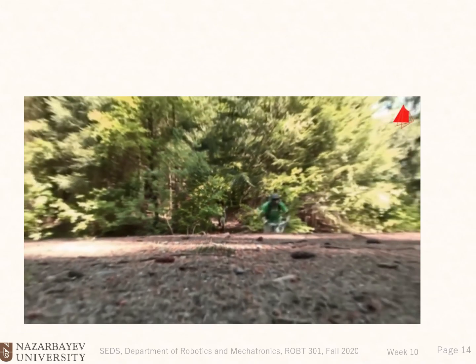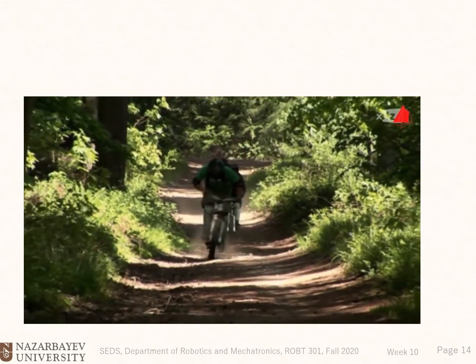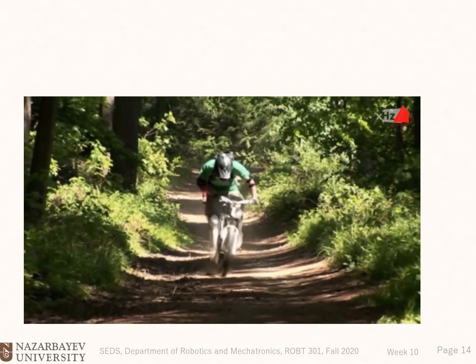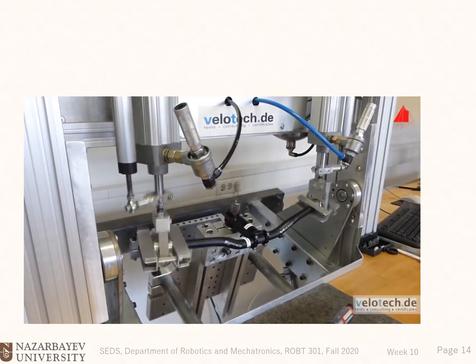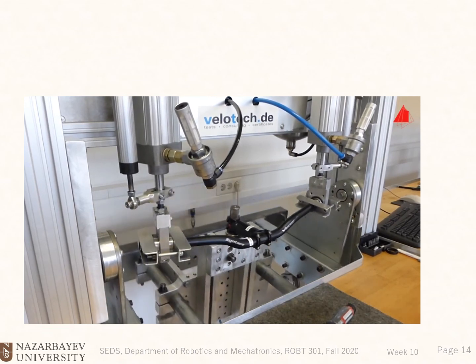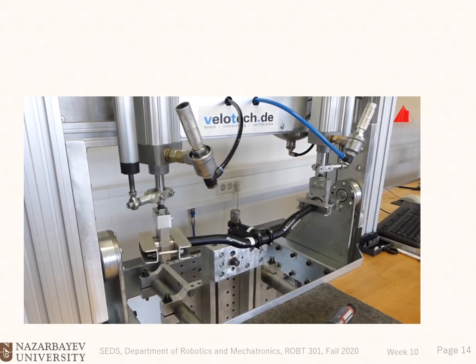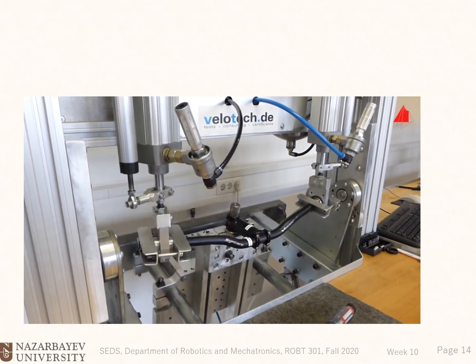Of course, most users don't load their components with a constant cyclic load, but rather in an irregular manner. Therefore, these components have to be tested under this type of loading, termed operational loading. In this test rig, critical bicycle components are loaded similarly to practical use. Stem and handlebar must endure the typical bending and torsional loads for a sufficient number of cycles. Only then are they approved for serial production. Moreover, the fatigue strength does not only depend on the material. The mean stress has an important influence, the shape, the surface quality, environmental conditions and much more. Not an easy story.